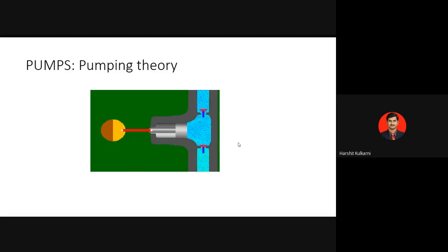Please remember this. Now, the movement you observed here, at present we have a system which is a kind of reciprocating pump, a reciprocating piston pump, wherein the piston movement creates the suction pressure and discharges. Similarly, this theory of pumping can be mechanized, or we can use different kinds of elements. Like if we use gears, can we have two gears, and because of the movement of these two gears, can a suction pressure be generated and can we displace a fixed quantity or volume of fluid? Is it possible?